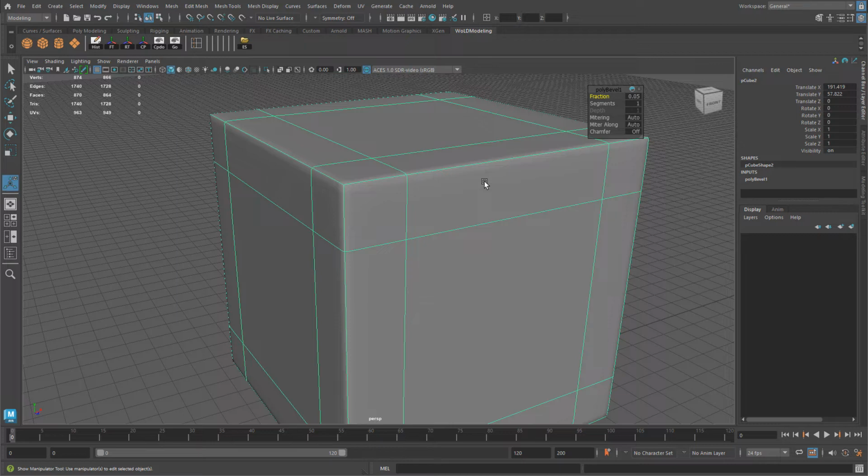And there's one more shortcut key. If you press 2, this will give you a low poly cage of the original mesh, as well as the preview for the high poly, subdivided cube. So the 3 shortcut keys are: 1 for the low poly object, 2 for the low poly cage and the high smooth preview, and 3 is your smooth mesh preview without the low poly cage.